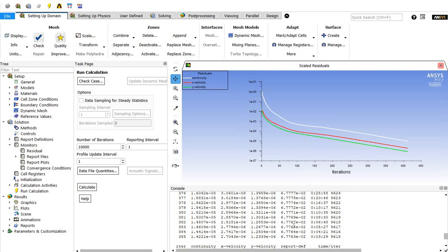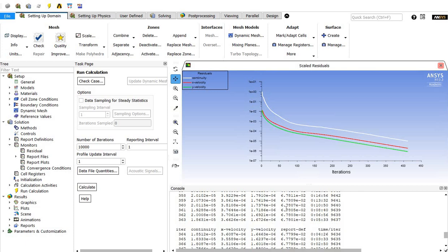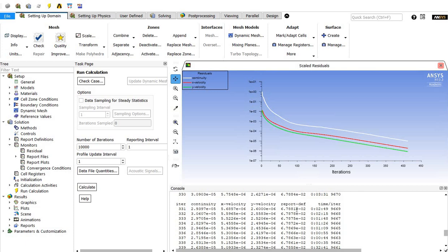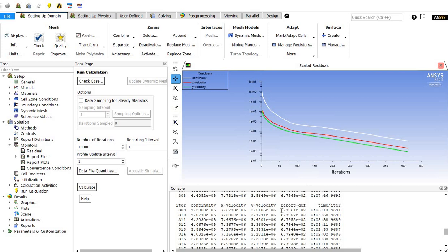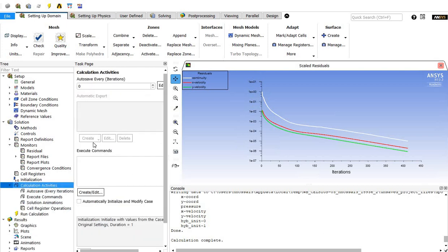If it was unsteady, like at a higher Reynolds number, where you are analyzing a turbulent flow, the drag on the cylinder wall will change, the average drag, and you will see this value will fluctuate. So this is my drag coefficient value, and they are all the same because this is a steady state. You can calculate the drag force from this value as well using the analytical equation. There was another way to plot it. If you wanted to plot it, I guess you needed to create a report in here. Maybe I'll show it later.